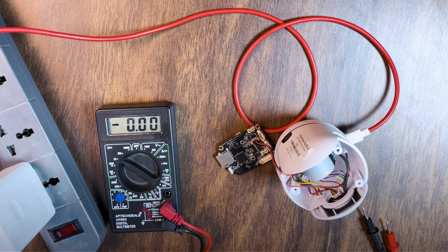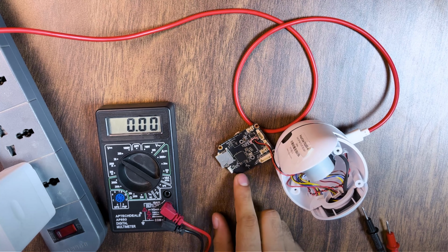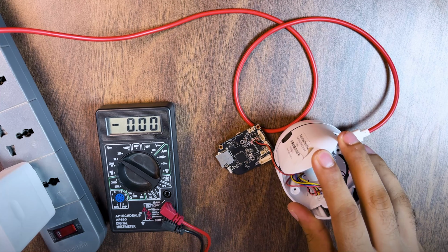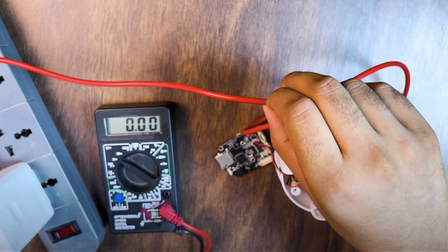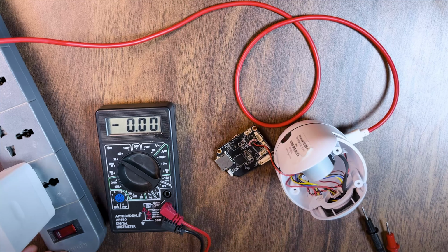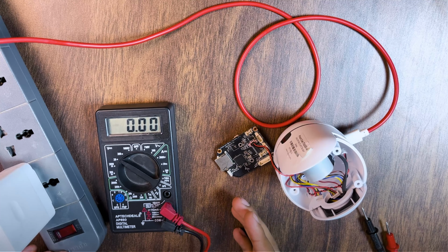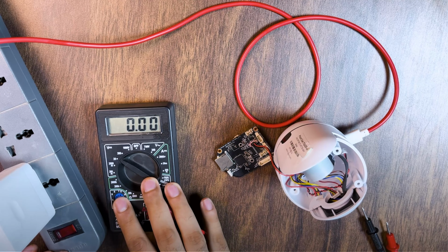Usually when you're trying to figure out which of the ports is RX and TX, you're going to look at the voltage fluctuation that it is receiving while the motherboard or the device is booting up. This is why I've connected the motherboard to the device it originally came from, and I've connected this device to the power supply over here, right, and the extension over here. And what I'm going to do is power cycle the camera again and again and check the value of the readings of voltage I'm going to get on my multimeter.